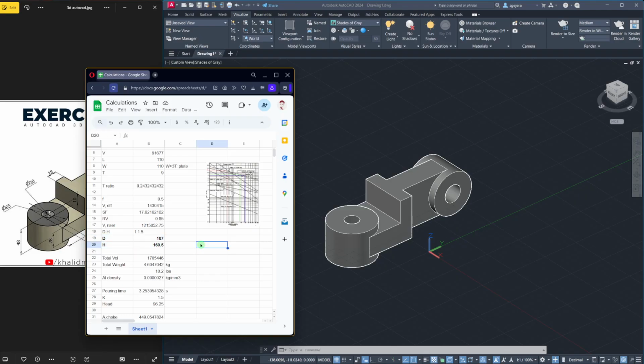So the riser is almost always a cylindrical shape, no? Kasi yun yung may highest volume to surface area ratio among all the practical shapes. If you think about it, the highest volume to surface area ratio na shape is actually a sphere, pero hindi siya practical na shape for a riser pagka nilagay mo na sa isang casting system, no. Kaya ang next best is the cylinder, no.